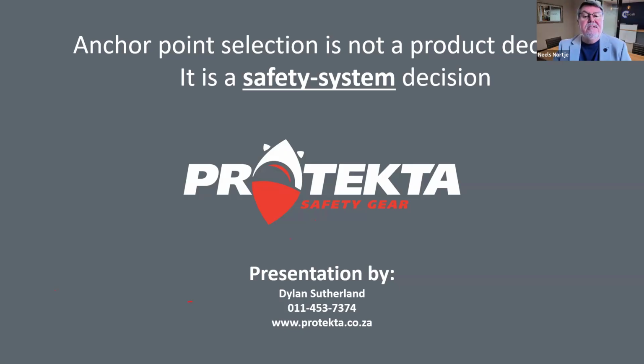Augustinus, hi, just need to know, the pull test device, it should be calibrated, right? It very much should be calibrated, good point. So annually, that should be calibrated and made sure that the readings are correct. Right. Thank you.